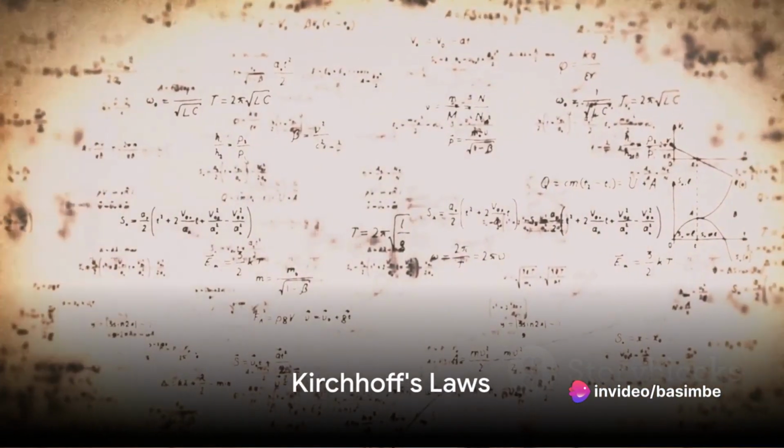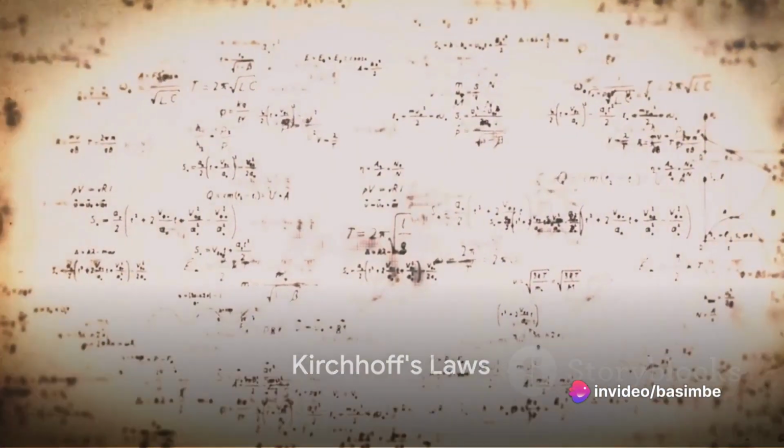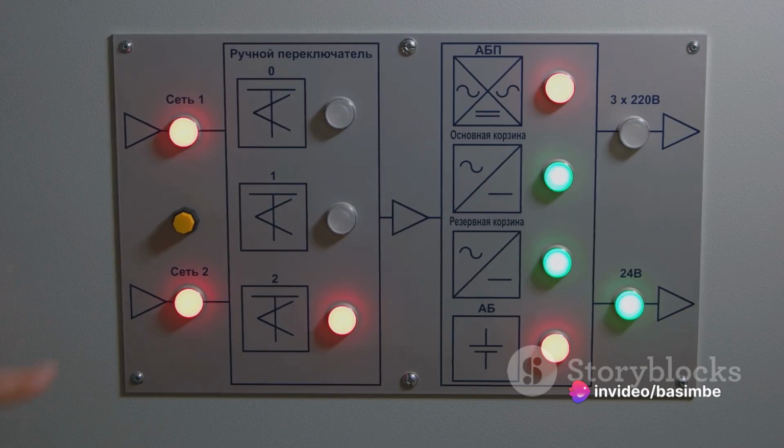Now let's add another layer of complexity with Kirchhoff's laws. Kirchhoff's current law, or KCL, states that the total current entering a junction equals the total current leaving it, ensuring the conservation of charge. Kirchhoff's voltage law, or KVL, on the other hand, states that the total voltage around any closed loop in a circuit equals zero, reflecting the conservation of energy.